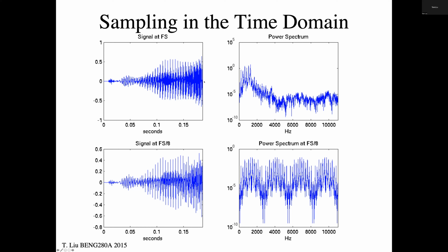Okay. And one way of looking at the outcome was to look at the Fourier transform of this signal. And so the Fourier transform is going to give us the representation of the sinusoidal oscillations in this signal at different frequencies. And here are the frequencies in hertz. This is a temporal sample. This is 150 milliseconds of data out to here. And then these are the relative amplitudes of the sine waves and cosines at different frequencies in hertz or cycles per second. So we're out here at 10 kilohertz. This is 2 kilohertz.